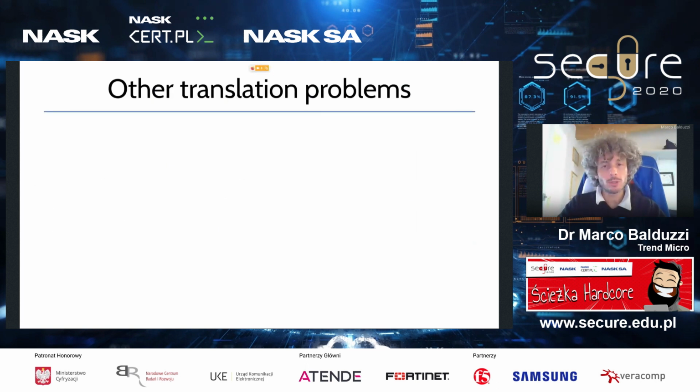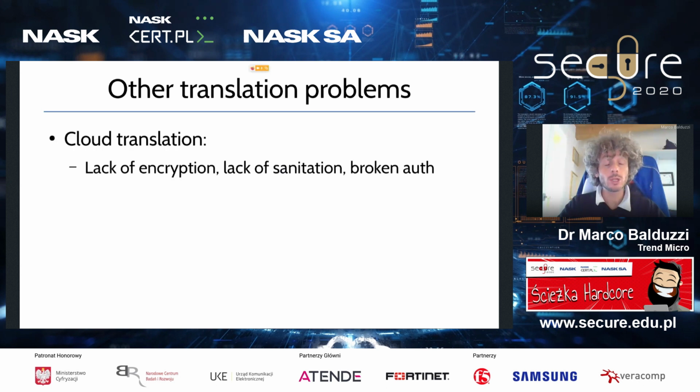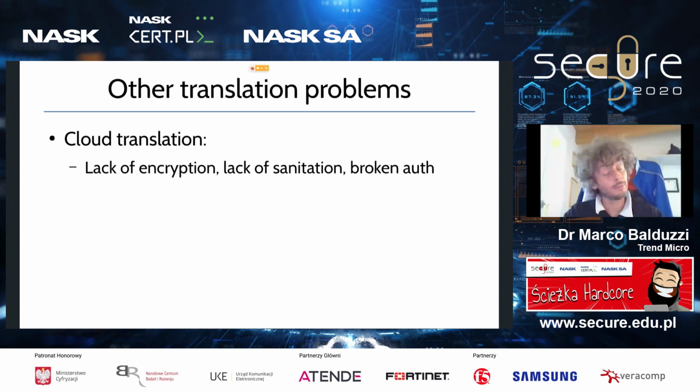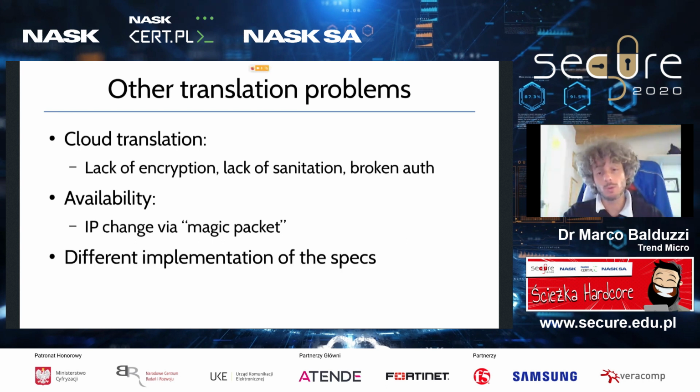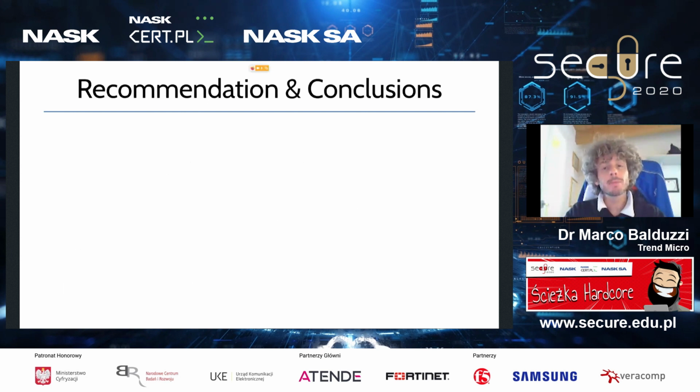There are a bunch of other problems I'm not going to discuss for lack of time. For example, how these devices integrate with the cloud, thanks to MQTT, so how they translate from Modbus to MQTT. There are problems with availability, the fact that you can reboot, you can change the default IP address of this machine. And there are also problems with different implementations of the specification. So even if Modbus is not a proprietary protocol, not all the devices correctly follow the specification of Modbus.